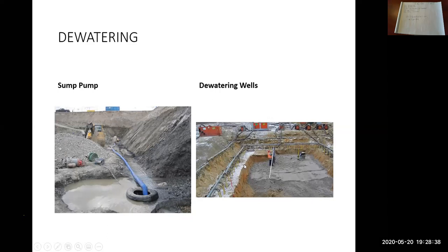So this other photo here is your well point dewatering system. So dewatering wells. Here's their excavation. Actually, this whole thing is probably the excavation. So these pipes here go all the way around, and they likely come around this side as well. Those are the header pipes. Coming down off of there are individual yellow hoses. Those connect to individual pumps.